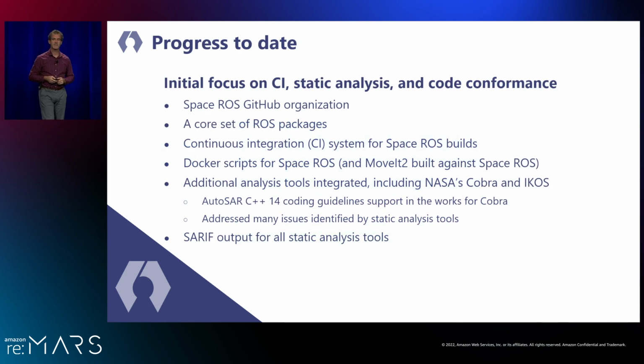We've been working on this project for about a year, and the initial focus has really been on static analysis so far and code conformance to the analysis tools. We've established a GitHub organization for the code. We've identified a core set of ROS packages, like what's in the core of Space ROS, and established a continuous integration system for the Space ROS builds. We've also put together Docker scripts so that you can automatically build Space ROS and try it out.